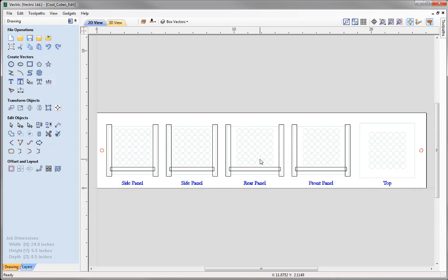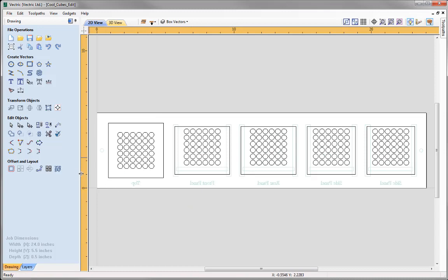So we'll then take the material off of the machine bed, and we'll insert the dowels into the holes in our spoil board, where we'll then flip our material over along the x-axis, and then we'll look at positioning the material for the bottom side on the dowels to align at X0, Y0, in which case we'd then secure the material in place, and then we're ready to machine the toolpath for the bottom side, where we're going to look at creating profile toolpaths on all of these holes to form some decoration, and then we'll finally run another profile toolpath where we're going to cut each one of these panels out.